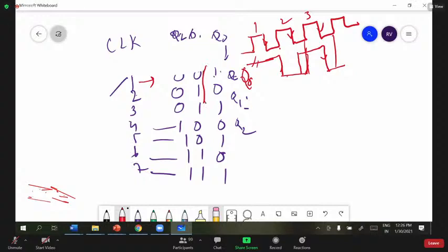See this. So this is 0, 1, 1. Initially it is 0. Then immediately during the negative going edge, 1, 1. Then immediately I can draw this up to here. Then immediately it is changing, 0, 0. So up to this 2, then 1. Like that you can draw. Similarly for Q3, how do you draw? 0, 0.